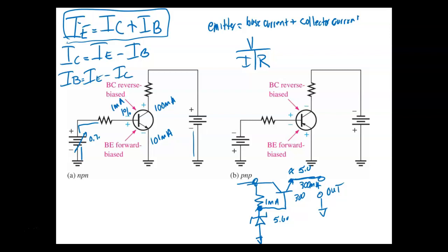So this is basically the way a Zener power supply would work: we would combine it with a bipolar transistor, because what can we get out of the bipolar transistor? A current gain, yeah. So we can run a lot heavier loads, but we still use the Zener just for the reference, right? You understand? And it regulates too, because if this voltage tried to drop down, it's going to try to maintain around 0.7 of a volt. So if it drops down, then it would automatically do what? Turn on a little more.